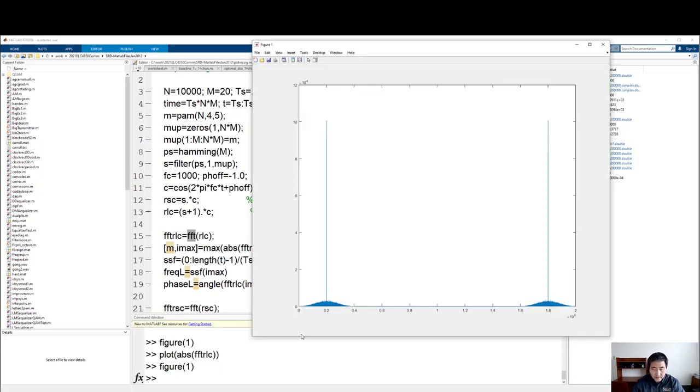So here's what we get, the frequency domain signal. It's a cosine function, so we have both positive frequency and negative frequency, and they are even symmetric. We do have a very strong carrier, because it's a large carrier: we're adding 1 onto my message signal. So here's my signal at a positive FC, and another signal at negative FC.